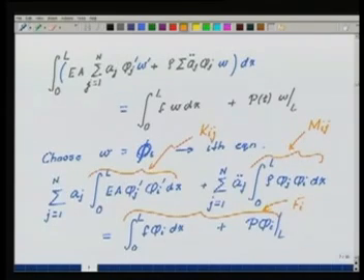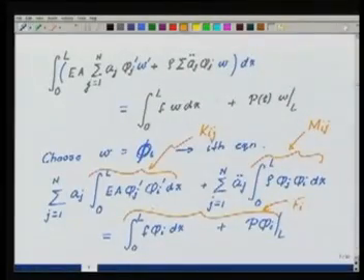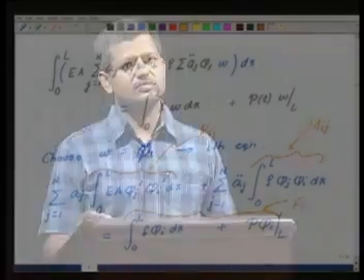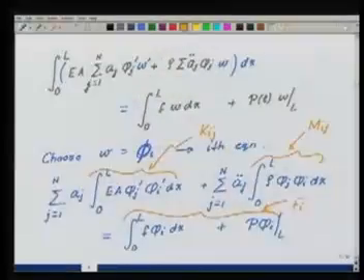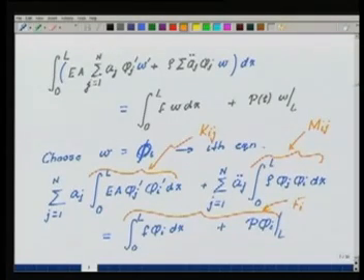Okay. You see another thing, that if my EA is constant with time, then the stiffness matrix does not change with time. It could change for certain problems, especially where I have plasticity, or when I am doing the finite elasticity problem where the area is changing with time, then in that case EA could change, and because of that the K could change. Here the mass matrix, again a similar thing, the density could change as the material is deforming for finite elasticity, but the way we have done things in this problem, the density does not change, so even this part, the M, also remains constant with respect to time.